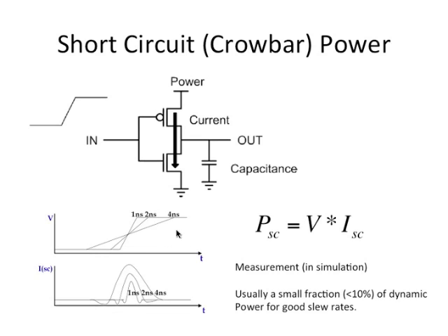That explains it: if I have an ideal step, there is no time for the output even to have changed, and I have very little short circuit current. The short circuit current is determined by the current through the PMOS, which depends on the gate to source and the drain to source voltage. So if my gate to source changes very fast and the drain to source has not fallen yet,